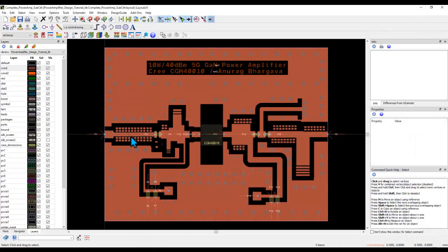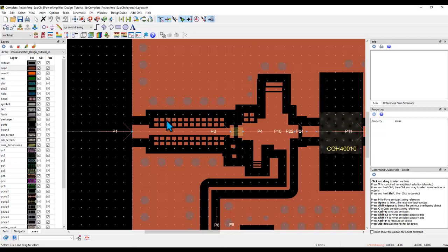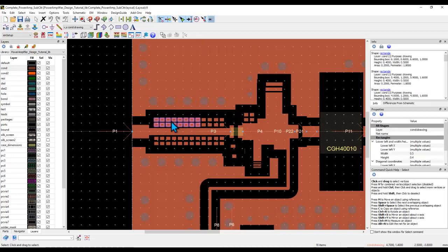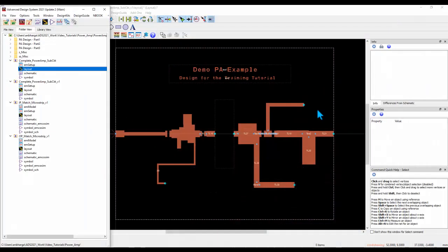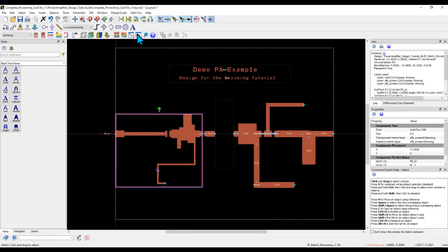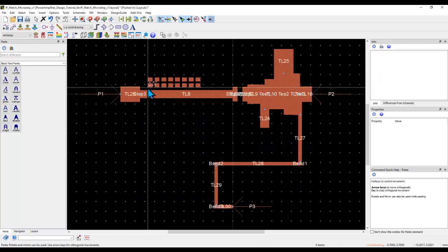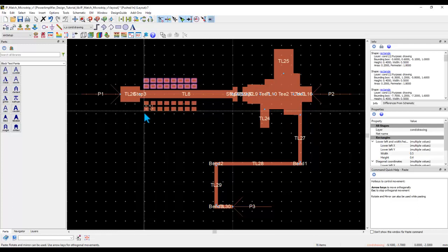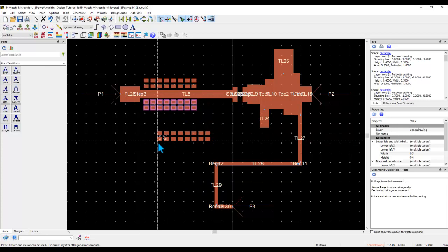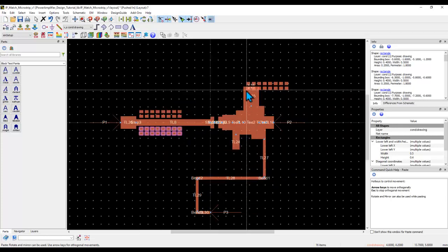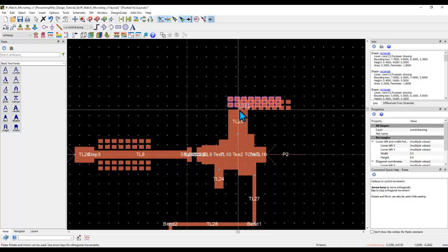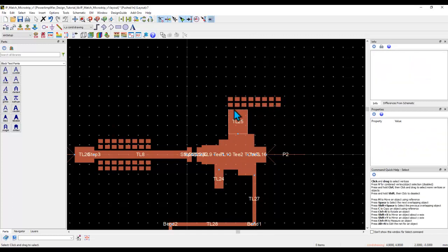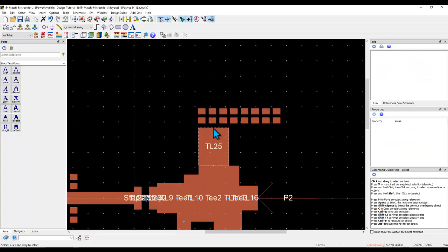So same thing I did in my actual layout, and here I can simply copy the portion of these. So you already know how to draw these rectangles. I don't need to teach you. And those rectangles I can push inside this hierarchy, and I can place it, because remember that design is something which I'm not ready to flatten for some reason, just to show you as a variety. And again, you can keep a few things here. Either for a stub, you can either keep the small rectangles, or you can keep a rectangle equal to this width.